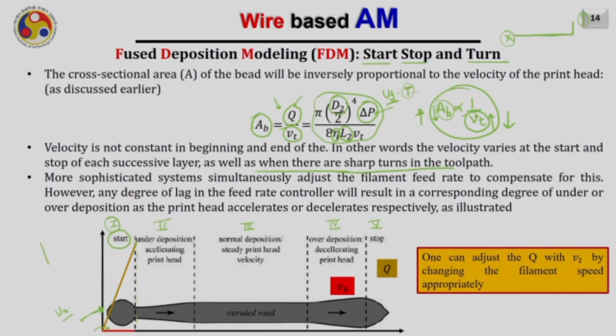As the wire has started feeding, it will also take some time for the material to start coming out from the nozzle. As a result, there is no velocity, but you are depositing some material through the nozzle, some finite value, because it will take some time to reach the desired wire feed rate. Some material will get deposited in the beginning like a dot, and that is what you will see when you immediately start your FDM process.